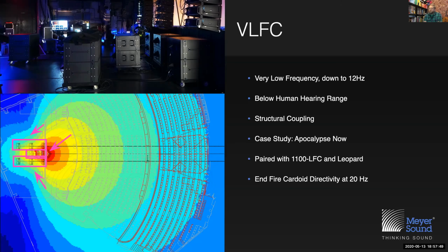So that when we're trying to control that very low frequency to get those long wavelengths to move forward, we have to space that end fire array twice as far, is the kind of general spacing I've recommended, as you would a more standard subwoofer end fire arrangement. So that was just one thing that kind of was like, well, I'll do a double, and yep, the math checks out kind of thing.